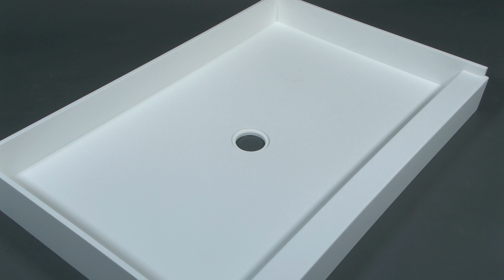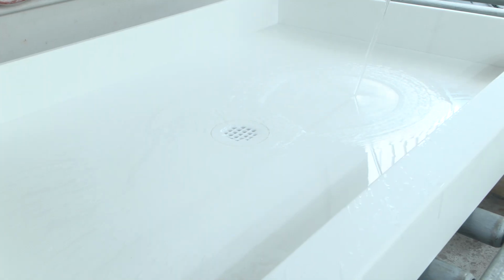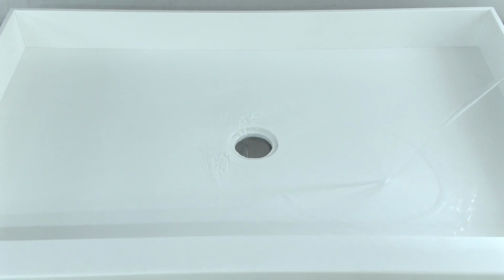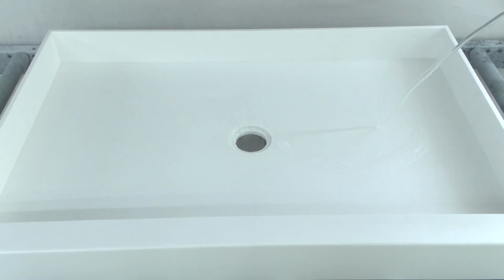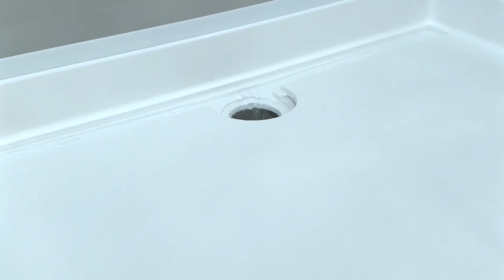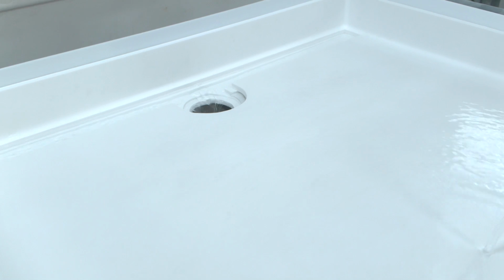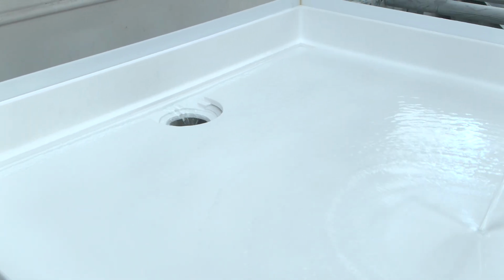The standard drain cutout option is your typical circular drain. The location on both standard drain and trench drain can be specified to align to plumbing. There is roughly a 2% slope between the outside edge and drain location. To ensure that every product has efficient water flow, all shower pans sent out by Grifform are water tested and documented.